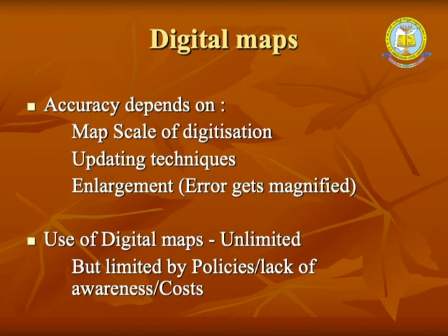Now, digital maps, as I mentioned just now, depend on the map scale, that is the scale on which the map is generated, and how you digitize. If you enlarge the same map, the error becomes that much more enlarged. So, you have to be careful in terms of what scale of map you are digitizing, and what tools you are using.